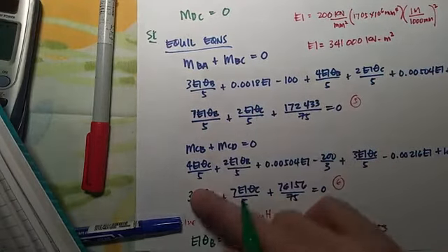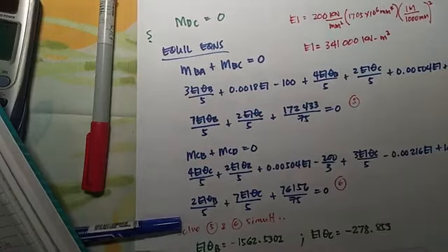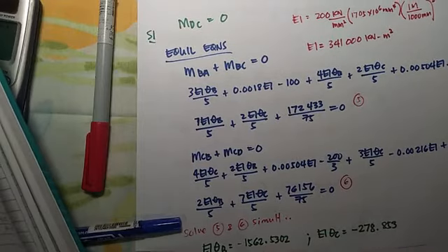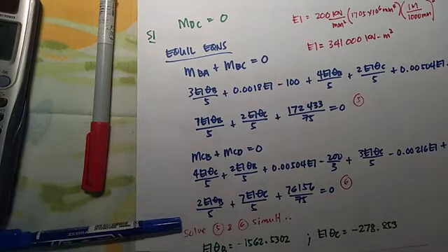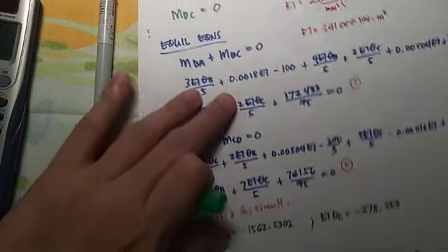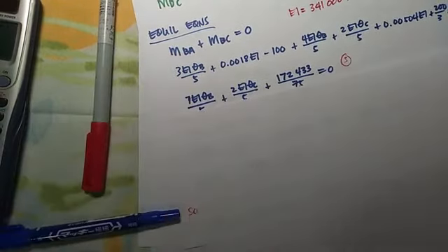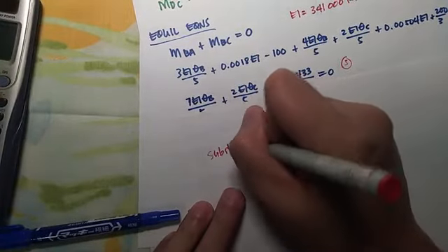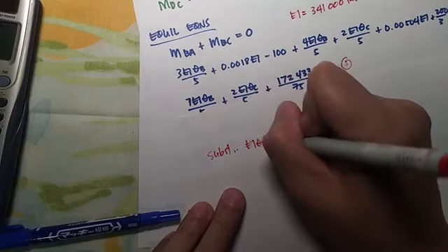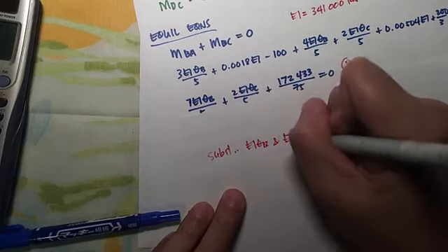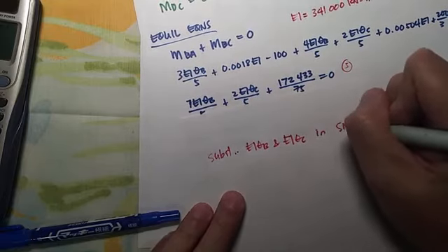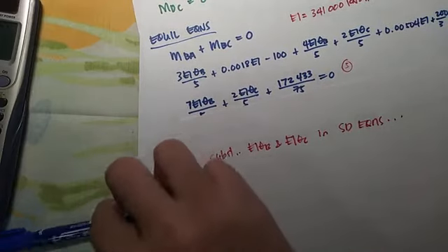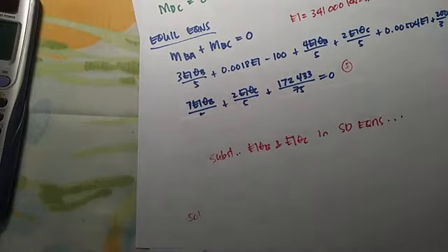Masolve mo, maka-cancel yung theta B, masosolve mo yung theta C. Then substitute back, makukuha mo yung theta B, EI theta B. Okay? So with that, substituting values of EI theta B and value of EI theta C in the slope deflection equations. Okay, so kaya mo ma-solve naman na dyan yung mga moments, diba?